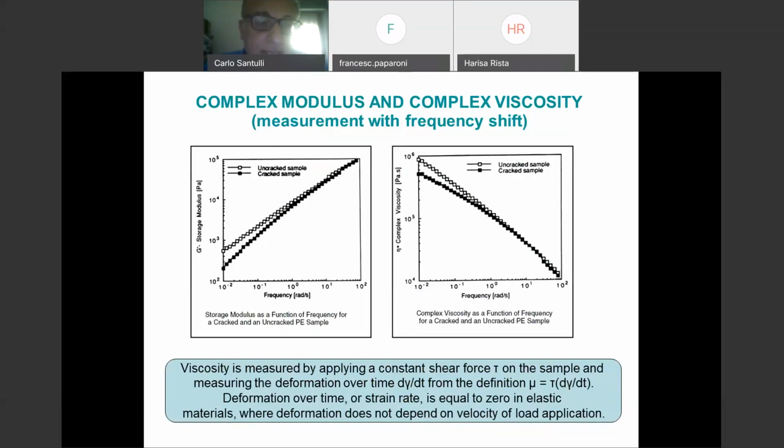it is true that you can have this is the shear modulus, and in practical terms, here you have a G. The viscosity here is represented in that figure with eta. In some literature they use also theta, but we usually use mu to represent the viscosity. And therefore, you know that viscosity is connected to the shear stress. So basically, you apply this shear stress and you allow the fluid to flow, depending on that coefficient, which is basically viscosity, which relates the shear stress you give and the flow you get.